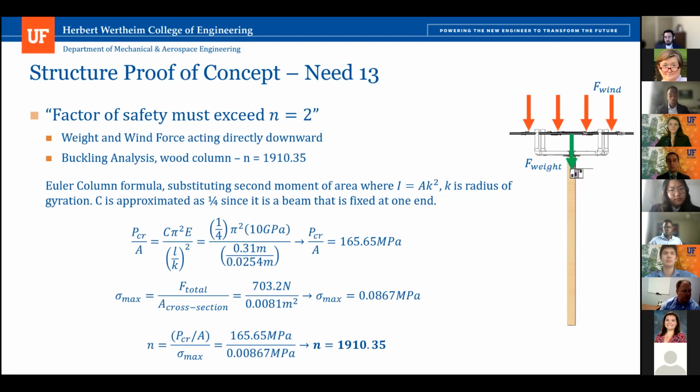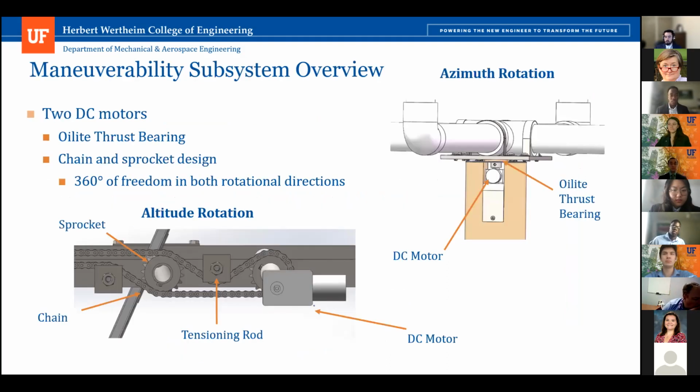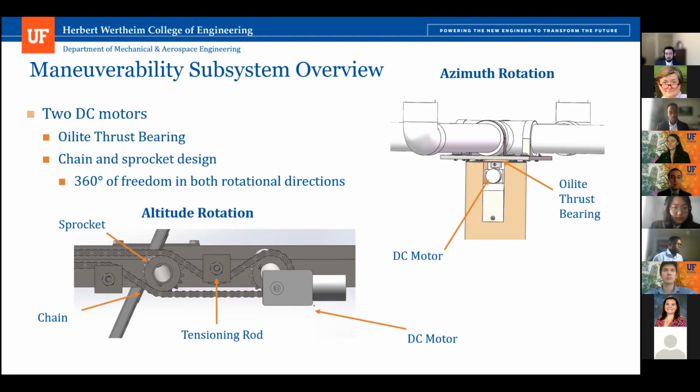Rick mentioned your chain drive and sprockets, and we were discussing it off to the side. Can you flip back to the slide where you're showing that? Yes. Right. So what I see here is you've got two lengths of chain going over the same sprocket, and you're never going to get that chain to line up perfectly with the teeth of your sprocket, which means you're going to be wearing parts prematurely. Something like that I'd be concerned about.